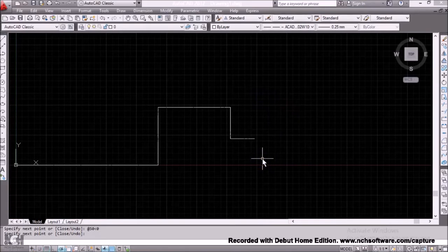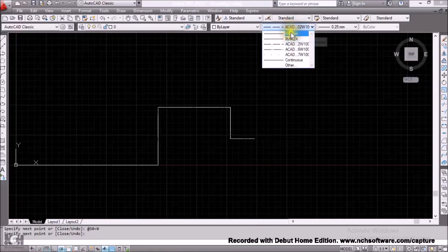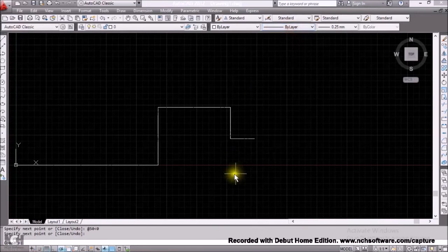So we just treated the relative polar coordinate method that uses angle to assign positions in AutoCAD. The last one is the direct distance entry technique. Let me change the line type here to a solid line. The direct distance entry technique is the most used method when we are assigning positions in AutoCAD.